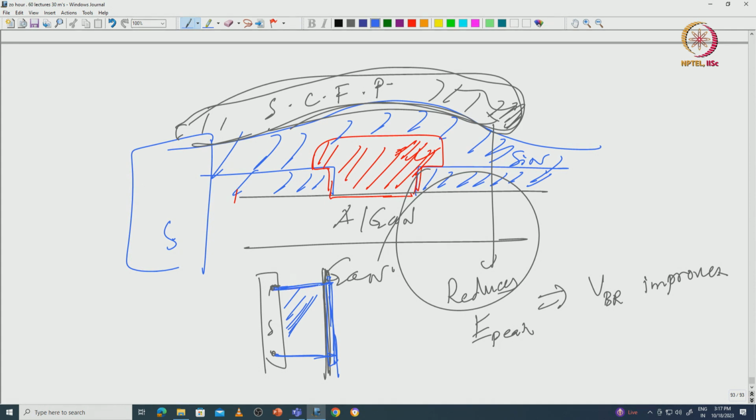So this is a source connected field plate, and the source connected field plate can come even deeper. There are so many designs: double field plate, triple field plate, step graded field plate, sunken field plate, slant field plate. There are many designs of field plate, but that is research level. Industry also adopts whatever they think is advantageous from the performance point of view and from the cost and economy point of view, etc. So this is in a nutshell the fabrication process.